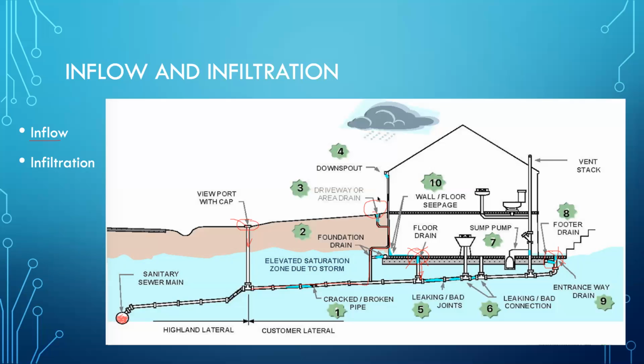The floor drains, those are bad. That's what the red X is, bad, dirty, no. Oh, and a downspout from the roof. Now, other types of getting sewage into the system, going through a sink, going through a commode, that's what they're supposed to do. That's not infiltration in the context of those rules. And going through the laundry sink down here in this basement, that's normal. Sump pump lifting stormwater out of the basement into the sewer, that would be a bad, dirty, no. So we get an X. So that's about all the examples of inflow in this diagram.